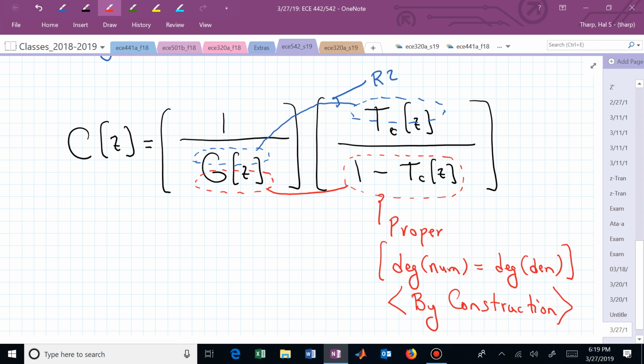And that will then cancel those unstable factors in the denominator of G of Z. So this is now restriction 3. That's how you can sort of think about restriction 2 and restriction 3 as indicated in your design formula. They take care of themselves if you set it up right. That's where those are coming from.